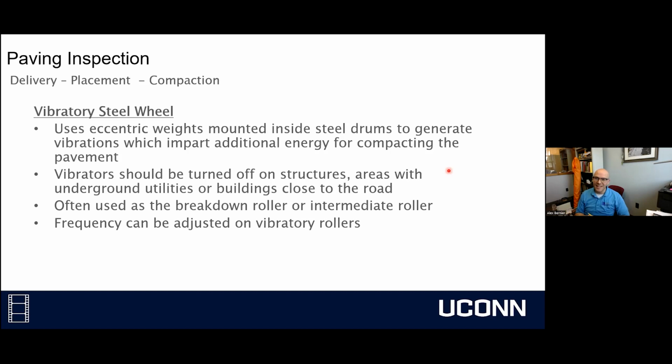If you're not vibrating fast enough, you create a condition known as washboarding, where as a car drives over it, it's going to make a noise on the tires, and it's actually going to degrade the pavement faster. If you look up I-95 singing pavement, we actually had a road built in our state a couple of years ago where someone was going too fast with a roller. And now on I-95 near Mystic, if you're going northbound, I believe, close to the New York, Rhode Island border, you'll hear your tires start to hum. So not ideal, right? We don't want that to be the case.